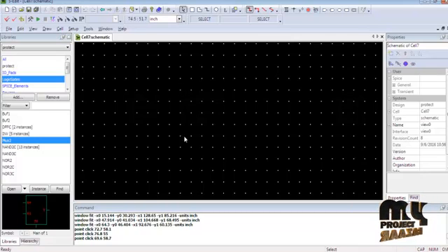After connecting the elements as per the circuit diagram, we save the file and select the corresponding library tools. After that, click the start simulation icon, then the window starts to run, and the corresponding output window will open, and also the corresponding timing window will open.